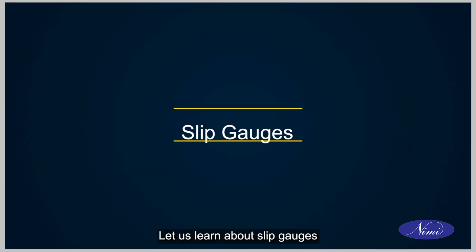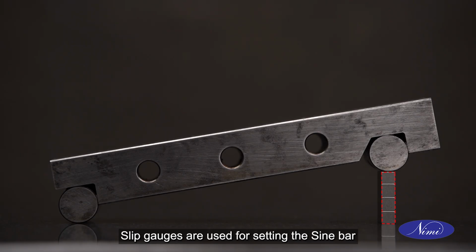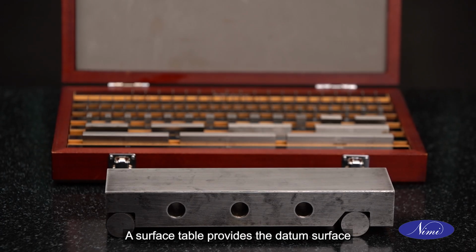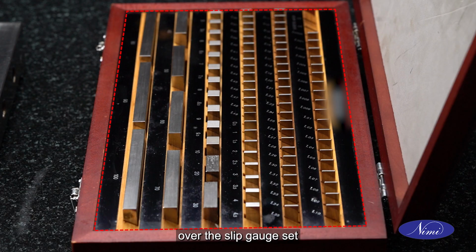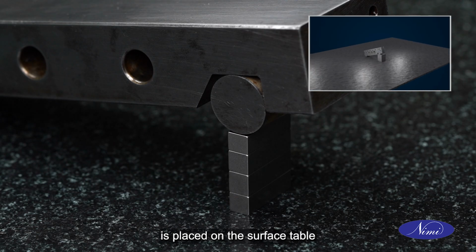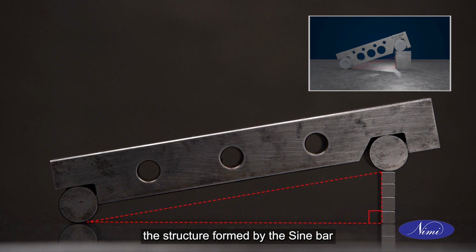Let us learn about slip gauges. Slip gauges are used for setting the sine bar to different angles or while measuring unknown angles using sine bar. A surface table provides the datum surface for the setup when sine bar is placed over the slip gauge set. If one roller of the sine bar is placed on the surface table and the other on the slip gauge set, the structure formed by the sine bar, surface table and slip gauge set forms a right-angled triangle as shown.